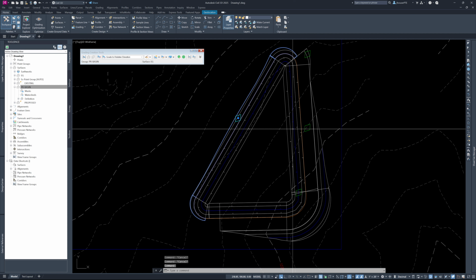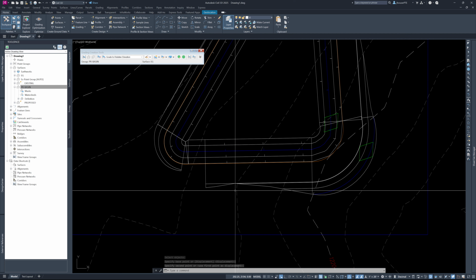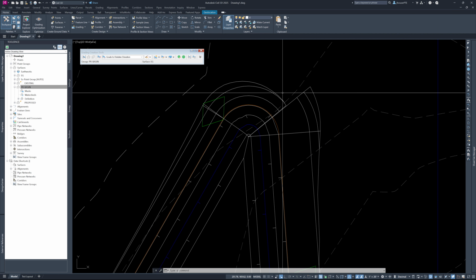Now the problem will be that our endpoints for the berm will need to be adjusted, because if we push it way back, now we might not be tying in all our contours. So you can see over here, this contour is not tying in properly. On the other side, it's definitely not tying in. We got to pull it way back to here in order to get it to tie in right. And wherever that daylight hits our original object, that's where the cut versus the fill begins. So we would have to pull this one way back. Well, let's just do that.